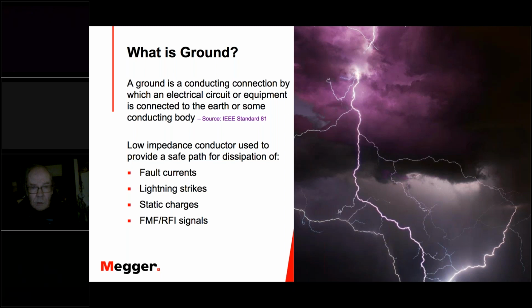Another one that's not thought about too much is static charges, especially in office environments where there's sensitive computer equipment, and in manufacturing environments where you have things like process control and so forth. Static can build up, and then it will spark to wherever it can find a place to spark to. If that goes into your equipment, of course, that can cause serious problems. So you want to have a good grounding system in place to constantly bleed that off so that it doesn't build up to the point where it sparks.